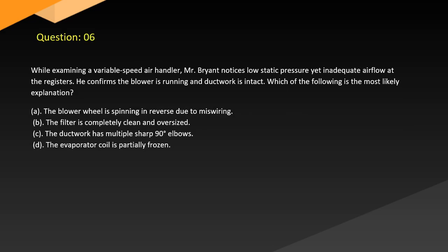Question 6. While examining a variable speed air handler, Mr. Bryant notices low static pressure yet inadequate airflow at the registers. He confirms the blower is running and ductwork is intact. Which of the following is the most likely explanation?